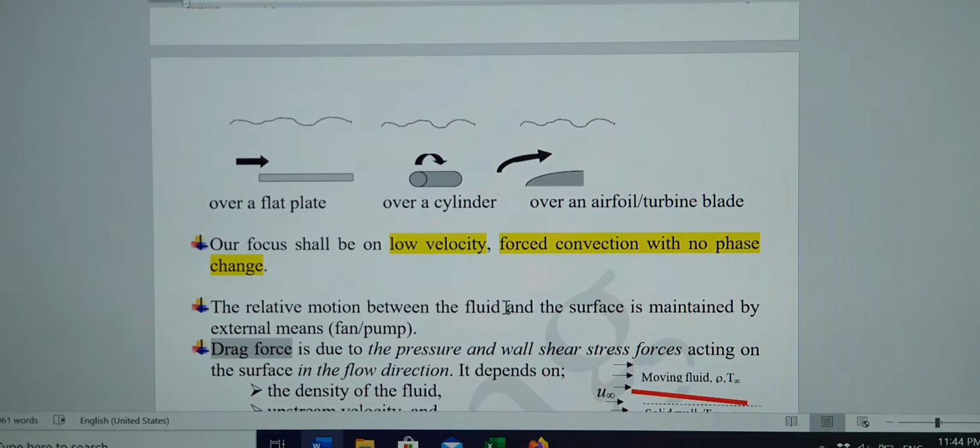Okay. The Nusselt number introduced earlier is hLc over k, and the subscript x here refers to the location along the direction of the flow. Now, the average means the value is taken from the leading edge over the whole plate up to the location where you want to analyze the heat transfer.